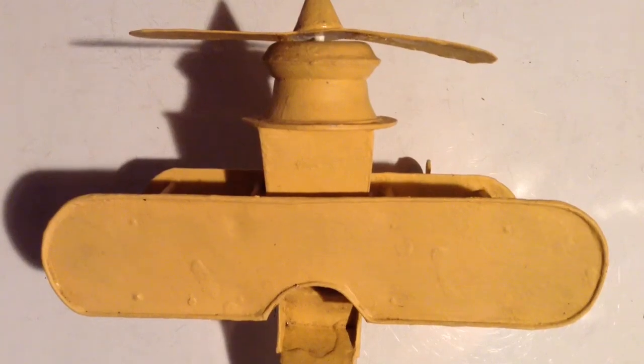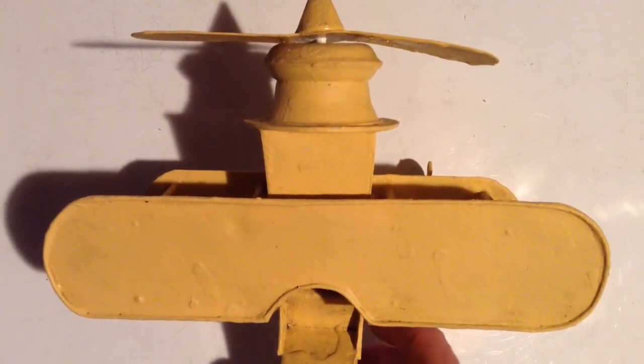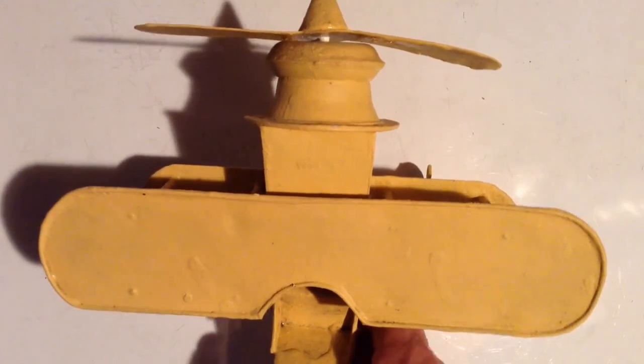Airplane pilots are taught about gyroscopic precession because pressing the rudder pedals causes the airplane to turn to the left or the right. If we mash the right rudder, the airplane will do like that. Left rudder does like that. This results in gyroscopic precession of the propeller, which makes the plane pitch up or down, depending on whether you mash the right or left rudder.